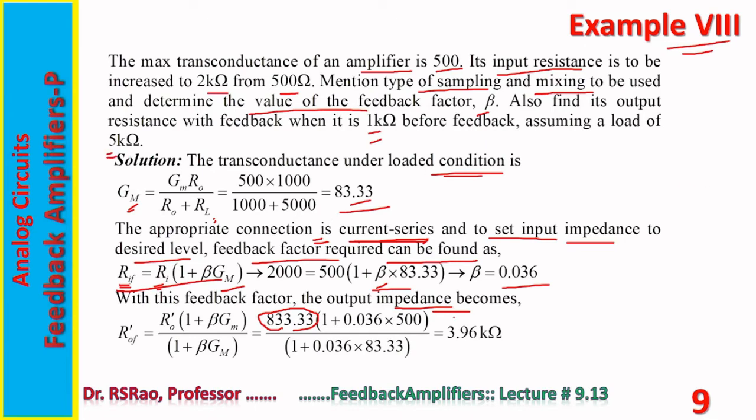So both the values: feedback factor beta is found equal to 0.036, and output resistance with feedback when loaded is also determined. It turns out to be 3.96K.